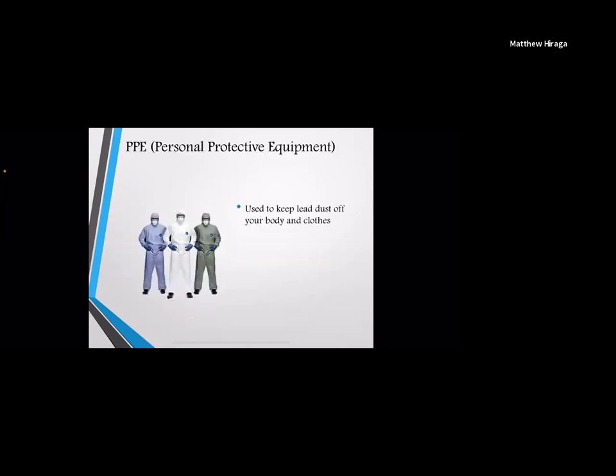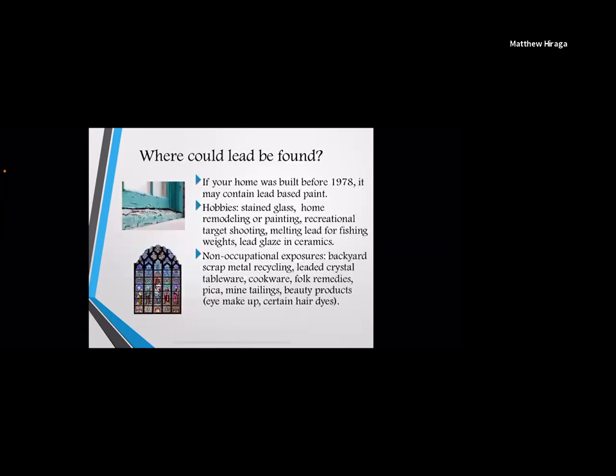Remember, you have to dust off any clothes in the work area, utilize a HEPA vac on some type of drop cloth, and clean up before coming out. And then this is just more examples of where lead could be found, right?